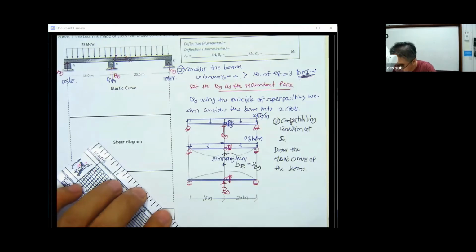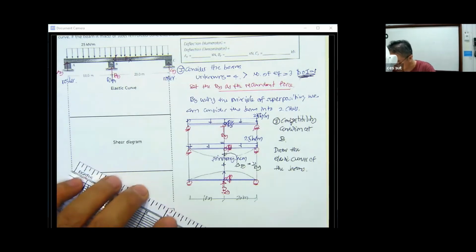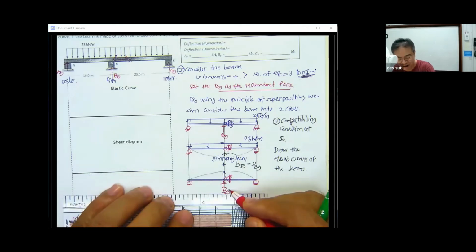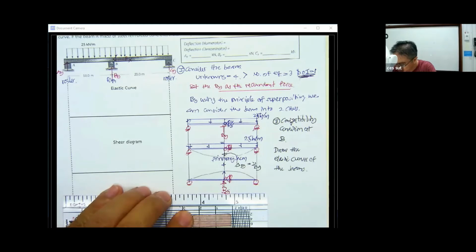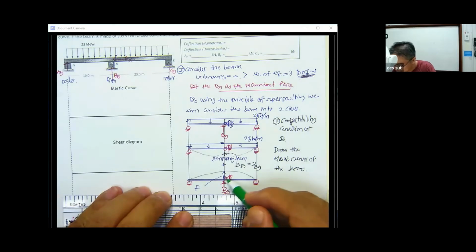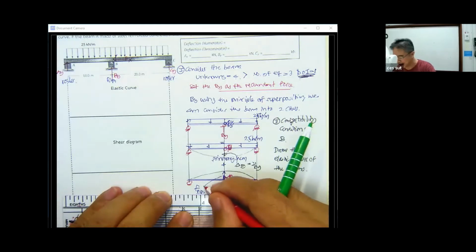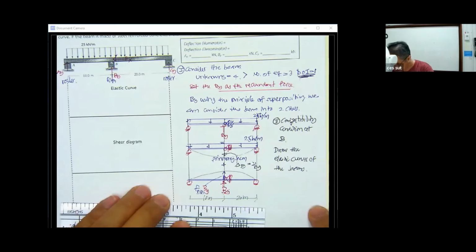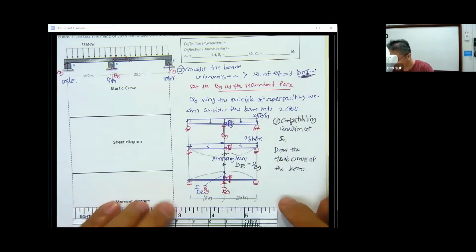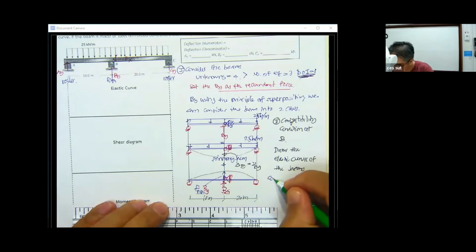But we are going to have the deflection over here. Since B sub y is unknown, usually we determine the deflection here by setting B sub y equal to 1. And then we set this to be the deflection of small f at point B, when the force is applied at B, and the total deflection is f times B sub y. Okay, and then we have this type of elastic curve. And then we consider the deformation, or consider the elastic curve.